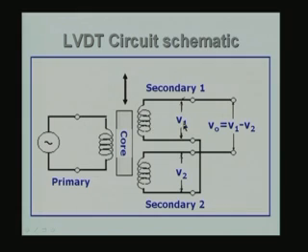Of course, this voltage depends on the turns ratio, this turns ratio of this to this, this to this and so on. So, this will produce a voltage equal to V 1, this is also AC voltage, this is also equal to V 2, this is V 2 which is equal to also an AC voltage. I have schematically shown it as the difference between two AC voltages, but how it is done is slightly different, which will become clear later on.